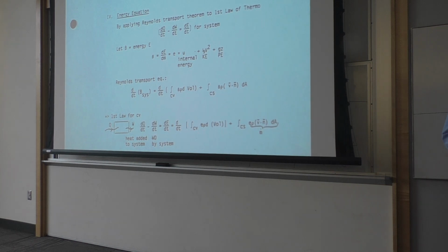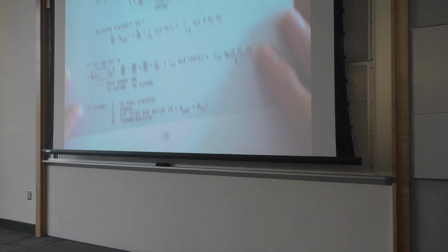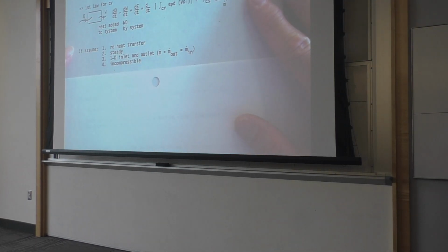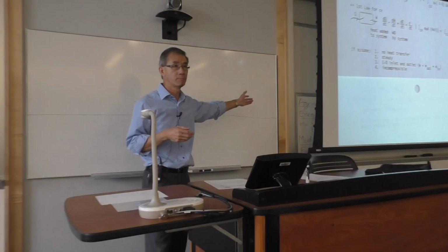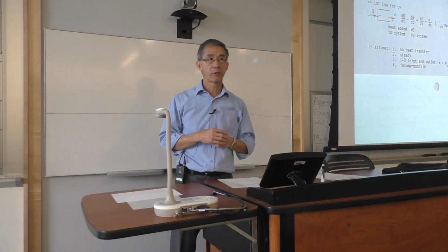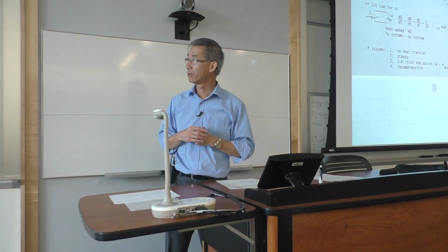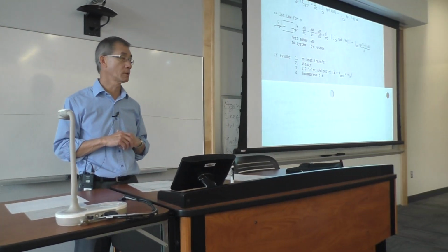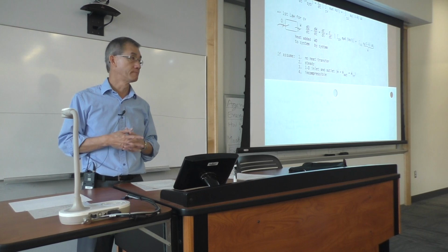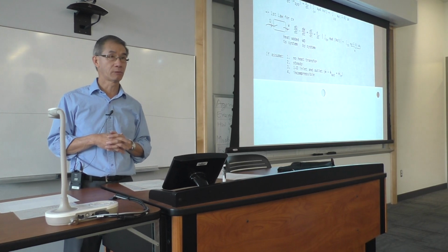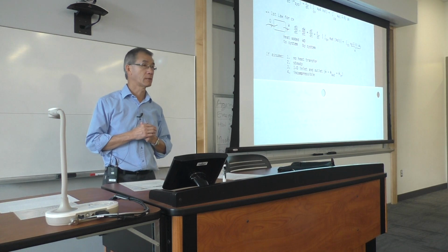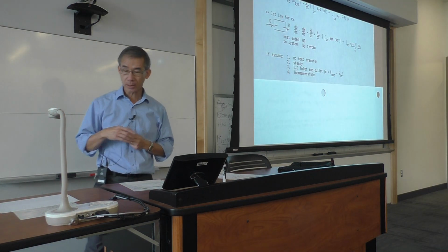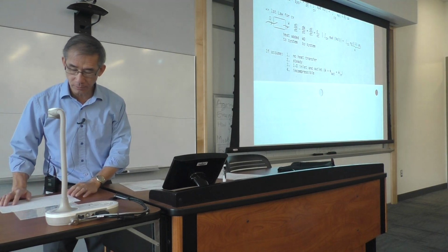But fair enough, I don't want to drill on this, but if you have a question, come see me after the lecture. So the additional assumption I make for pipe flow, so that at the end I get the equation behind the screen with the shaft work in head and the frictional head losses, is no heat transfer, which is very fair for flow in a pipe. There's no significant heat transfer, and even in machinery like a pump or turbine, external heat transfer is negligible. So the Q becomes zero.